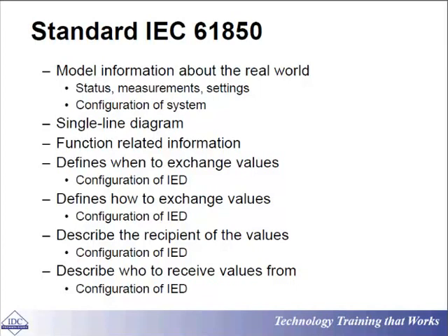So what kind of configuration is that? How many transformers do you have? 1, 2? If that's 2, are they running in parallel or not? So this is what we mean by configuration. Definitely SLD, single line diagram, and also all sorts of other information regarding, let's say, the SCADA RTUs, the PLCs, and the relays, and all sorts of things, the configurations of them.